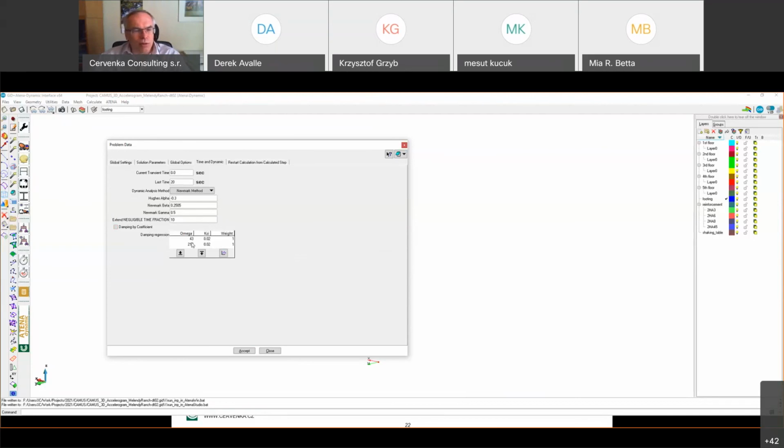So because we need to define these two parameters, ideal is to define this psi for two eigenfrequencies. Typically, for instance, the first two. We will define the omega for the first two frequencies, and the corresponding psis. They can be, of course, different, but it's 2%.